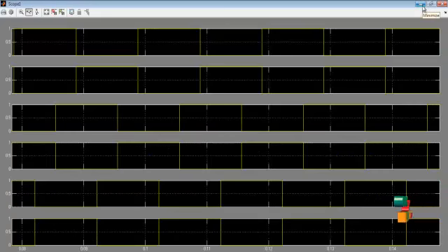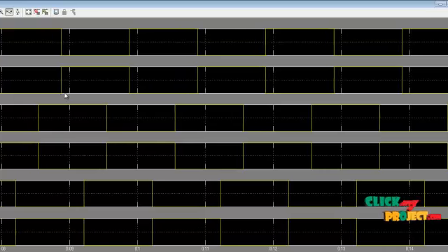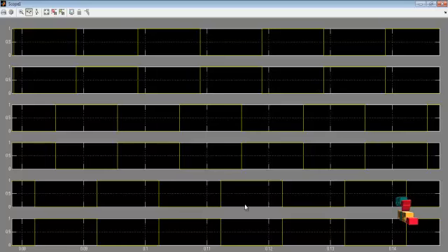This is the pulse waveform generated for the power electronic switches to trigger. Here we use the space vector pulse width modulation technique. This inverter has 3 legs, each leg having 2 power electronic switches, and they do not trigger at the same time. We can see that in the pulse waveform. This is S1, and those two scopes are connected in each leg, so the waveforms will differ. This one is on at that time, this one is off, and this one is on, and this one is off. Similarly, all the waveforms are generated and connected to the power electronic switches. Thank you for watching this video.